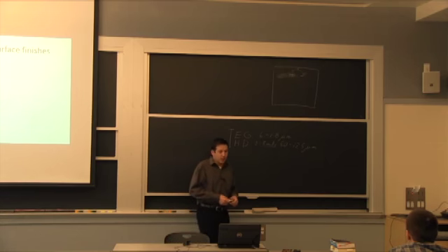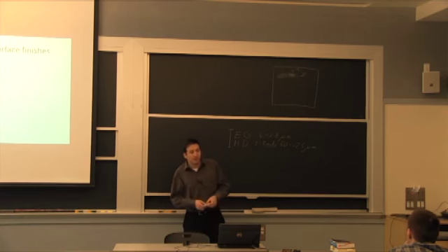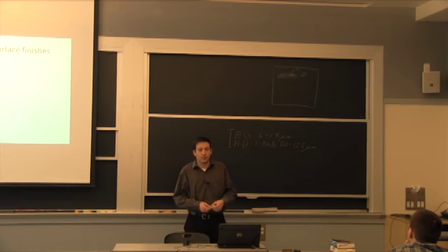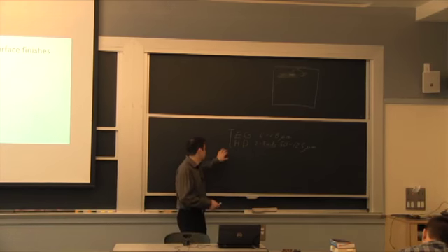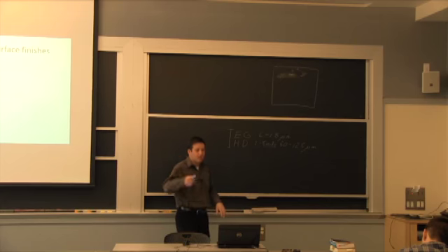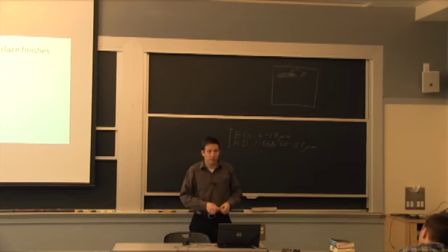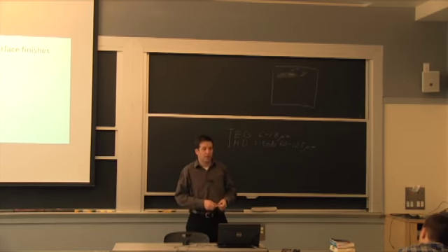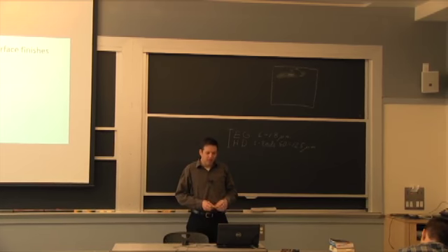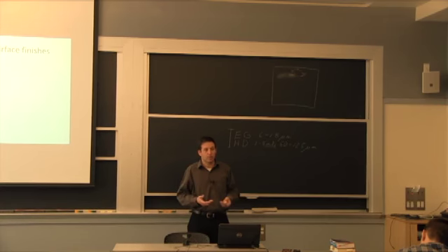Now, it's not a guarantee that you won't have rust marks. If you really scratch a piece of structural steel that has a galvanized on it, it will typically turn red or brown. Now, it's not going to lose much thickness, and that's really what we're looking for.